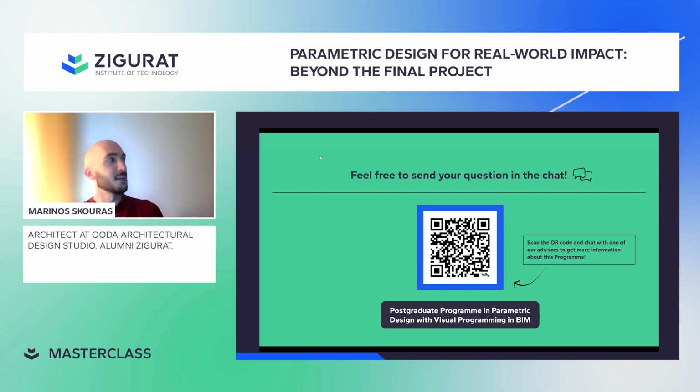Okay, parametric design in my daily work. Right now, I'm trying to push a little more toward more sustainable approaches. Using Grasshopper, this kind of visual programming, helps me do a lot of analysis and create designs, for example passive design that is parametrically driven.